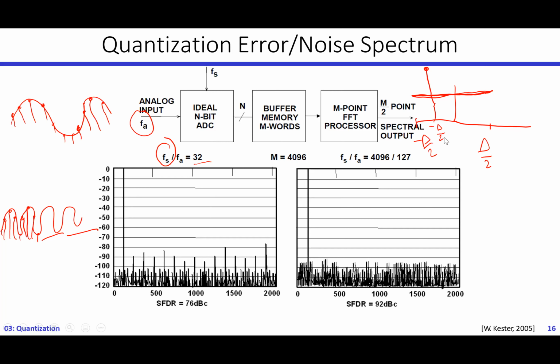Yes. Okay, now if it takes certain values, it means it's not uniformly distributed, which means it depends on the input voltage. That means you will have harmonic distortion in your FFT spectrum, in the output spectrum of your signal. Now look at this example here.